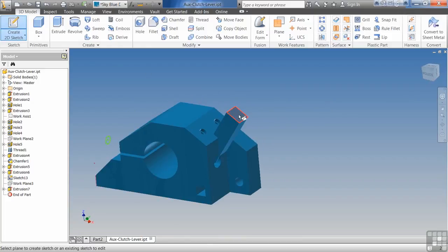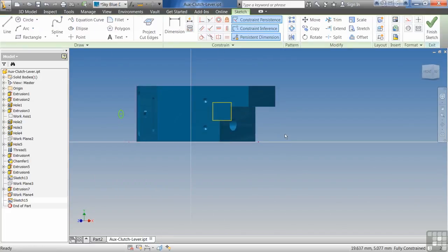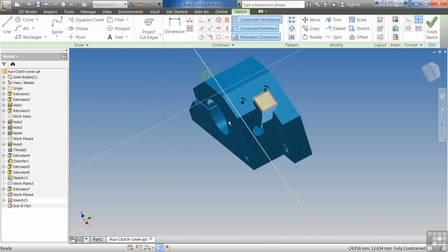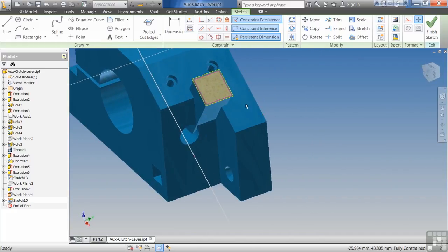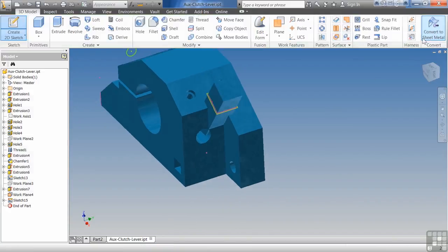If you say 2D sketch, you can also go in. So if you wanted to go inside an object to set distance, so say 12.5 millimeters there, you can hit F7 to slice my graphics, project cut edges, and now I'm working inside of that extrusion to do something else. I could do maybe a sweep around the outside, do some kind of groove. It's very easy to get in there and work on that. Later on, we're actually going to get into work planes and faces with axes and work points and be able to get even more complicated.